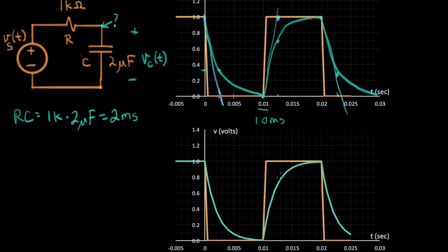So what we're comparing is this to that. And that's pretty similar. That's not bad. And that tells me that our output signal, our voltage on the capacitor, is following the digital signal fairly well and is reaching its high level and is rapidly coming down as fast as it can. So let me do one more problem, and we'll change the capacitor value.